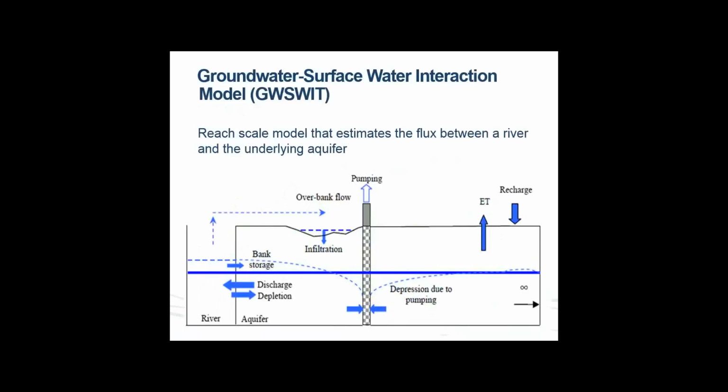To look at this model in a little bit more detail, the model is based on analytical and empirical solutions to the groundwater flow equations, and it includes processes like pumping, overbank flow and the bank storage discharge relationships, evaporation, floodplain infiltration from diffuse and irrigation sources, and it's suitable for unsaturated and saturated connections.